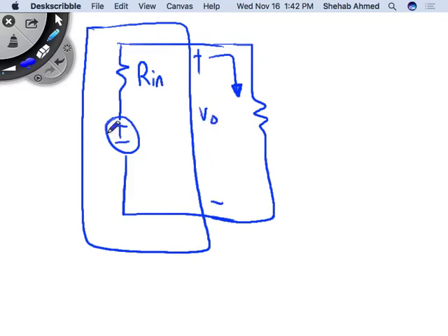If you don't change the duty ratio, let's say you have a power converter with a fixed duty ratio. Remember, this power converter has an inductor with a resistor in series. It also has a switch with a power loss, a voltage drop across it. It also has a capacitor with an ESR. So all of these things I'm modeling as internal.